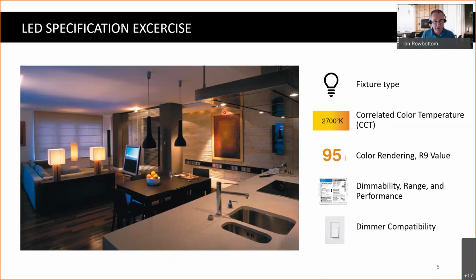Typically residentially we do 2,700 Kelvin to 5,000 Kelvin, whereas commercially we're more in a 3,000 to 6,000 Kelvin, a much cooler white, a much bluish, more blue white than in the residential that wants the red tones.